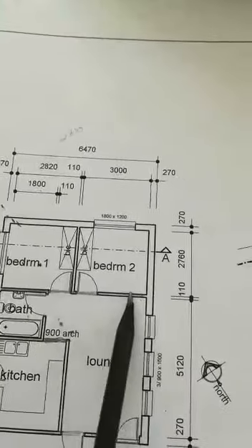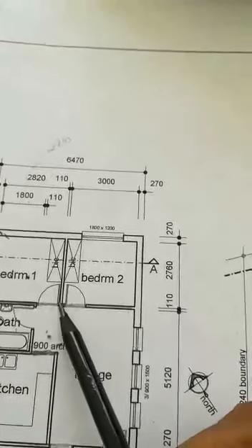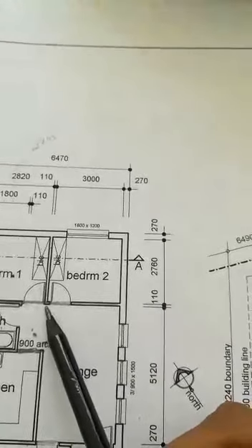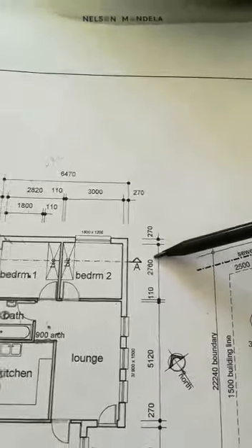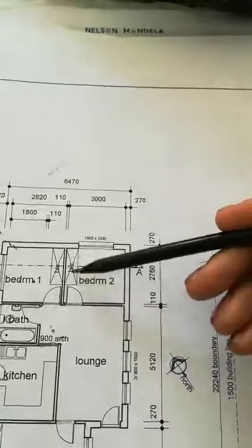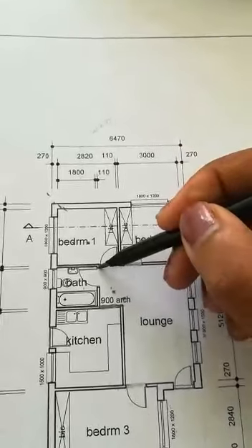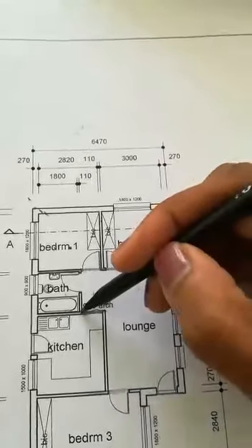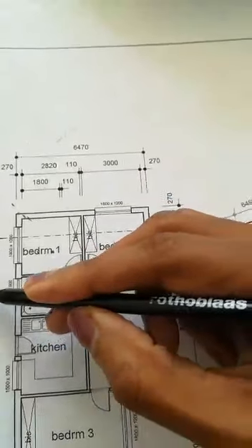Now remember, because I've measured this line through, which means that my vertical is going to end before. It's not going to come and end at the bottom of my line. It's going to end there. So then I take that dimension, which is now going to be 2760 for my vertical. And then I come here, and then I'm also going to measure in between my walls for my vertical for this one. So I'm going to take that dimension as is, and it's 1,800.